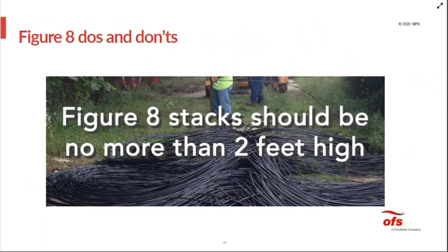Figure eight stacks should be limited to no more than 2 feet in height. And that basically is to limit the weight of all that cable on the bottom layers. So if you see you're getting up to about a 2-foot height, it's time to start your second figure eight.